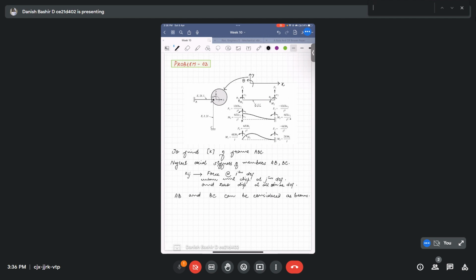So we have to see the necessary forces that will cause displacement along one coordinate while maintaining zero displacement along all the other coordinates of the beam. Okay, the ends A and C are fixed, and hence the joint B will have three possible displacements x, y, and theta that I already mentioned.